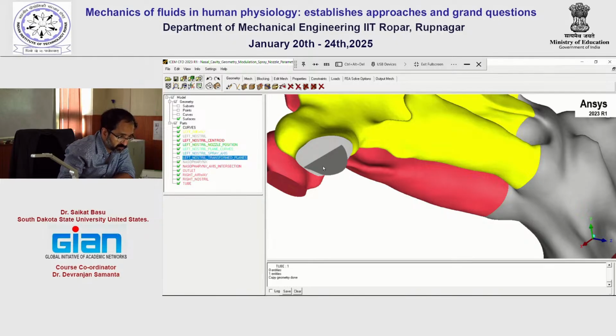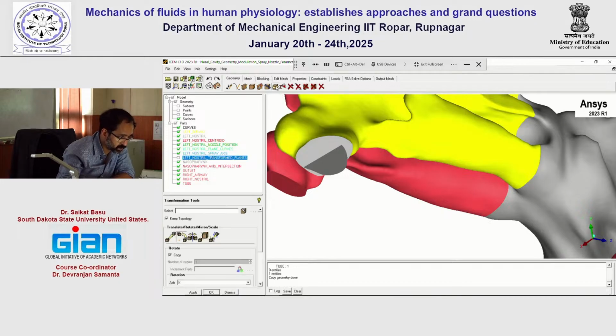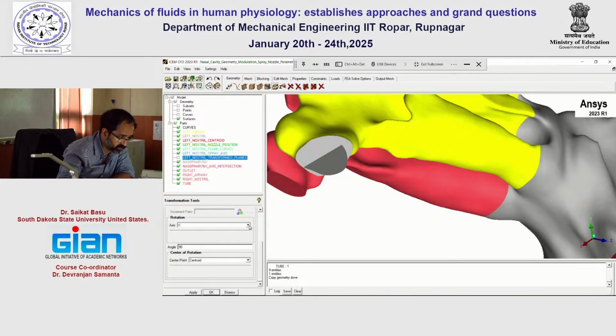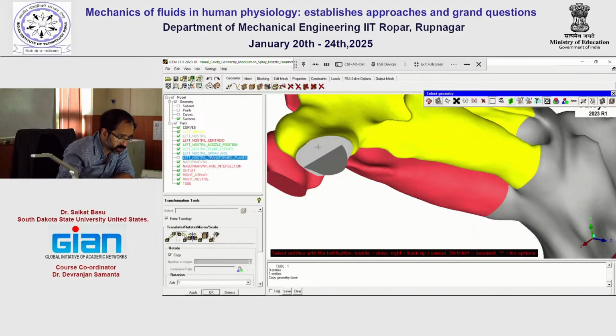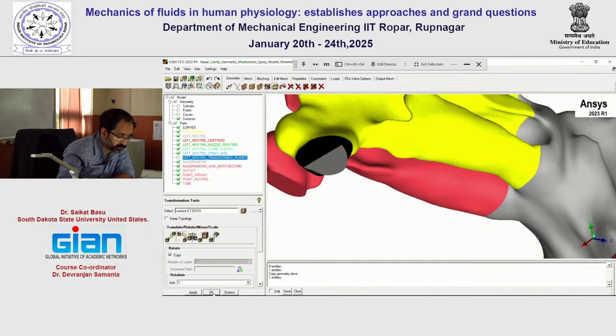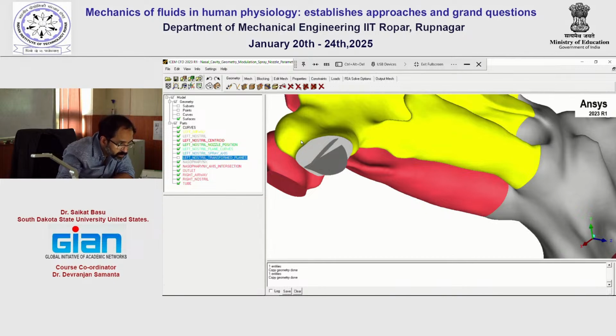So you see that I have created a new plane that has rotated, but it also cuts through the centroid. But just one transformation is not enough. We have to do two of them because we want the intersection to be a single point, which is the centroid. So for that, let's go back to the same step, but now let's rotate the original plane about a different axis. So let's pick Y. Still make the rotation about the centroid and go here and here. Middle button click. Okay.